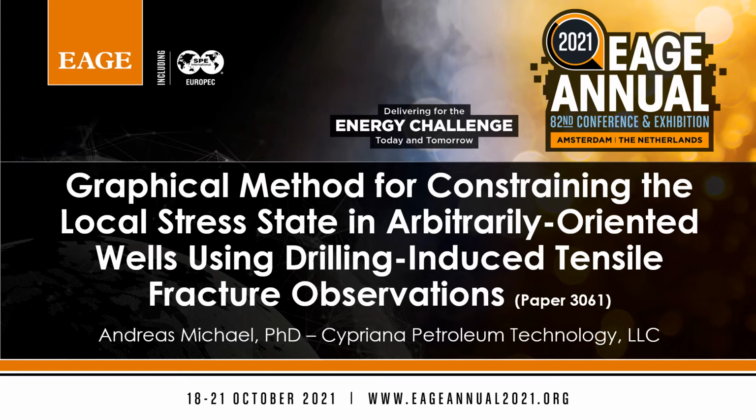Those drilling-induced tensile fractures leave a distinct signature on the image logs, and they have been used in the past to constrain particularly the magnitude of the maximum horizontal in situ principal stress.